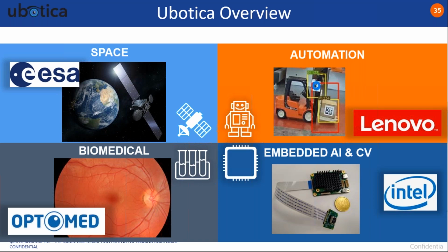We have developed lightweight toolkits, what we call the CVAI and also DPE, which in some ways take some of what OpenVINO is doing in terms of inference, but actually are able to do it in a lightweight manner, and also are able to use the image processing capabilities of the Myriad device, which is something you cannot do right now when you're using the NCS devices.